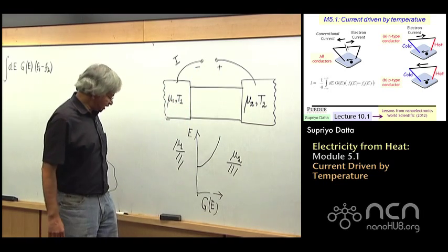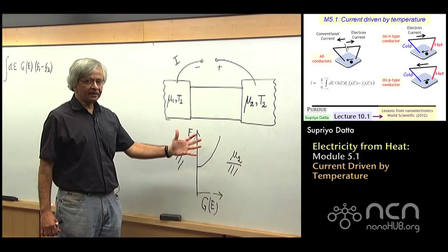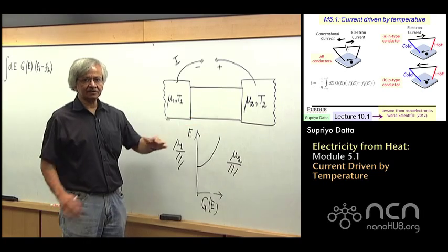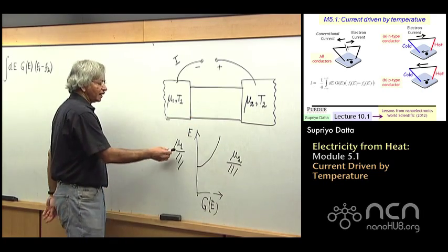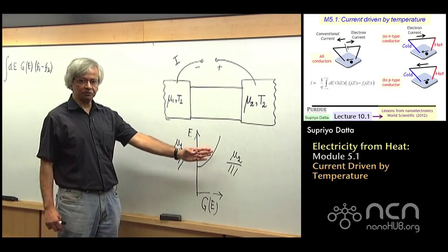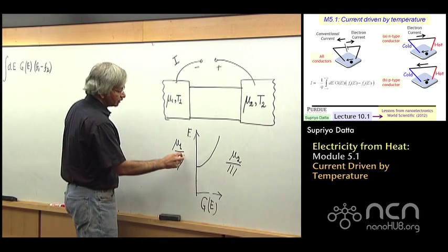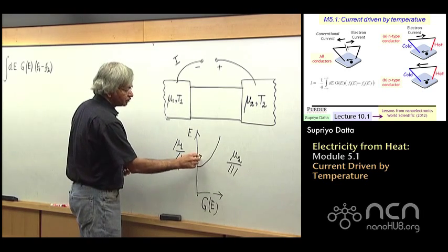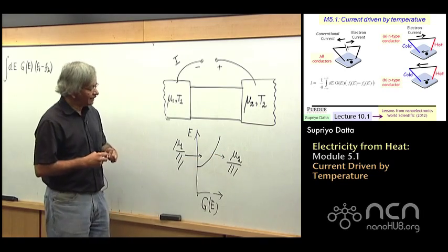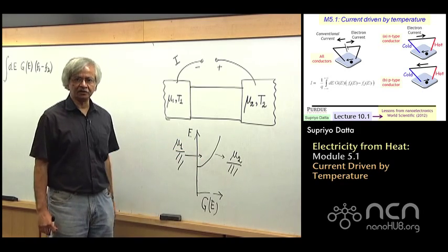And then current flows, and we discussed that we can understand this current flow in terms of this idea that you've got these 2 contacts. Because of your battery, the 2 have different electrochemical potentials, this mu1 and mu2. And current flows because one wants to put electrons into the channel and the other wants to pull them out. And that is why in this energy window around the electrochemical potential, currents flow.